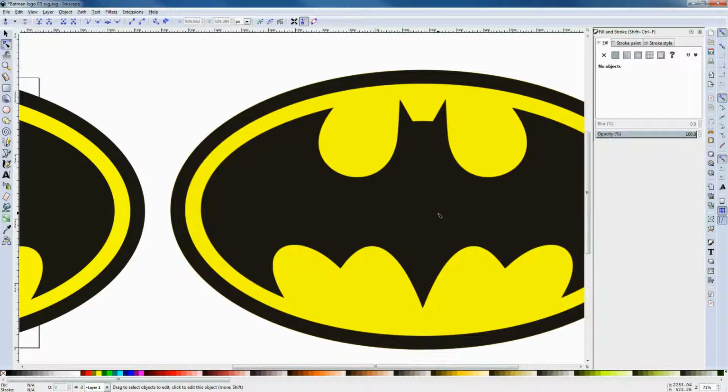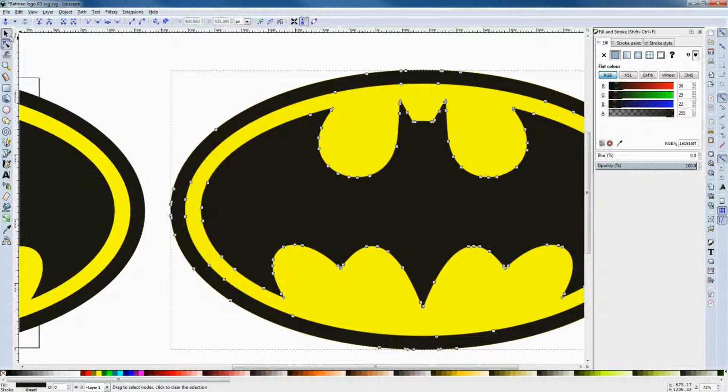And what I've found is that if I control the actual pixel size of this graphic, let's just get the selection tool instead there. If I look at the actual width and height, this is 1881 pixels in width and 1089 pixels in height, give or take a few decimal places. So if I bring this across right now, it's going to make a graphic which is 1881 millimeters in width, which is far too big for what I want. I'm imagining that I want to make this into a piece of jewelry. So I'm going to try and bring this down to a dimension of, let's say, 50 millimeters in width.